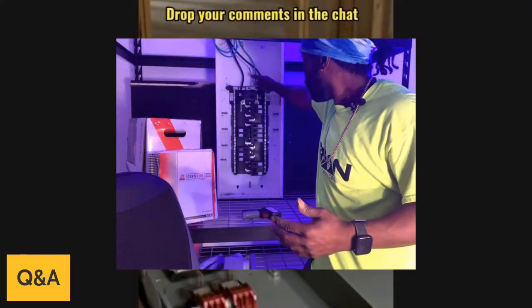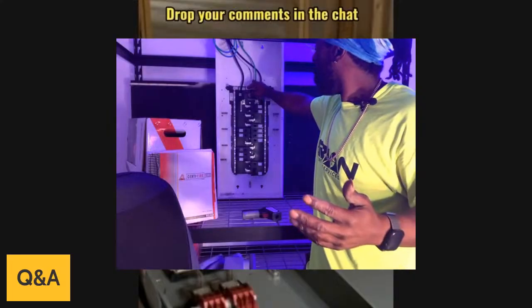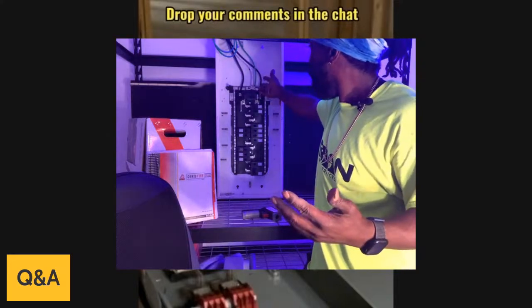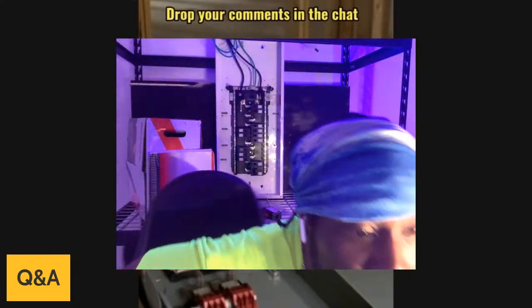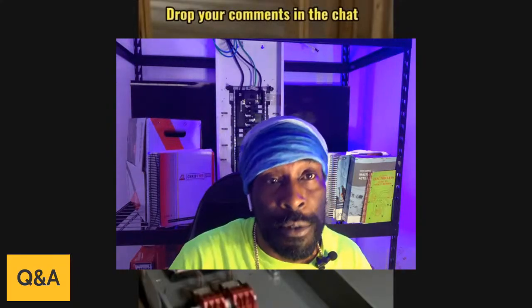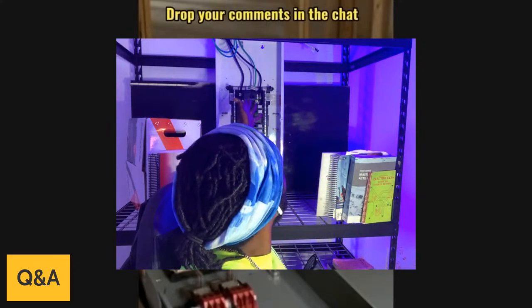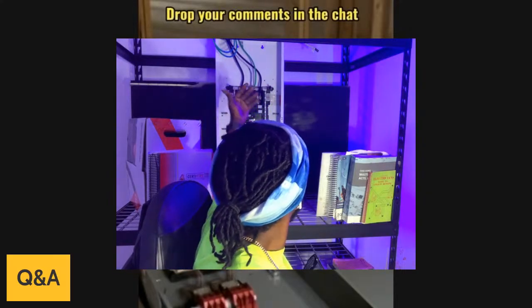So as you can see, this right here is taped with white tape. In order to identify my neutral, I have to tape this with white tape. And you can see right here, these are my two hots, which tie into here. So basically, that's how you go about installing a residential regular 200 amp panel, 300 amp panel, 400 amp panel. A lot of the panels are not going to have the lug situation like that, depending on the panel itself.